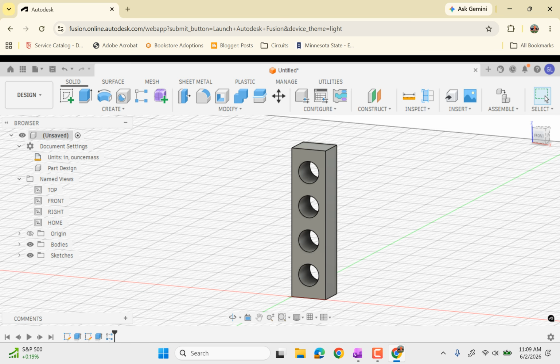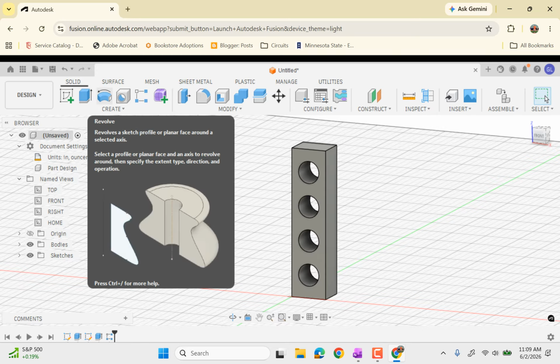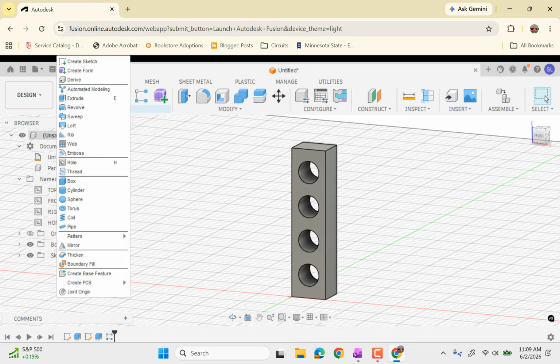And that's the thing again, like if you're doing a part that has 150 spokes on it, the last thing you want to do is spend a whole afternoon making 150 separate things that are identical. So this pattern, and if you are making spokes, by the way, you wouldn't do it in a rectangular pattern because they need to follow a circular path, and so you would go to, I think it's called the radial option, circular pattern.